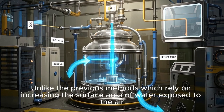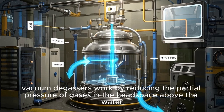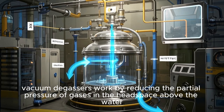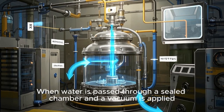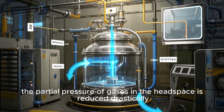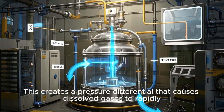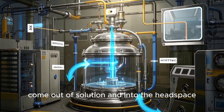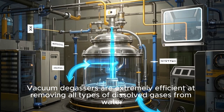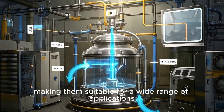Unlike the previous methods, which rely on increasing the surface area of water exposed to the air, vacuum degassers work by reducing the partial pressure of gases in the headspace above the water. When water is passed through a sealed chamber and a vacuum is applied, the partial pressure of gases in the headspace is reduced drastically. This creates a pressure differential that causes dissolved gases to rapidly come out of solution and into the headspace. Vacuum degassers are extremely efficient at removing all types of dissolved gases from water, making them suitable for a wide range of applications.